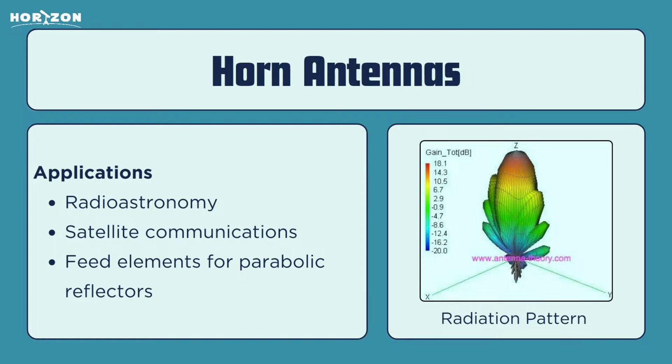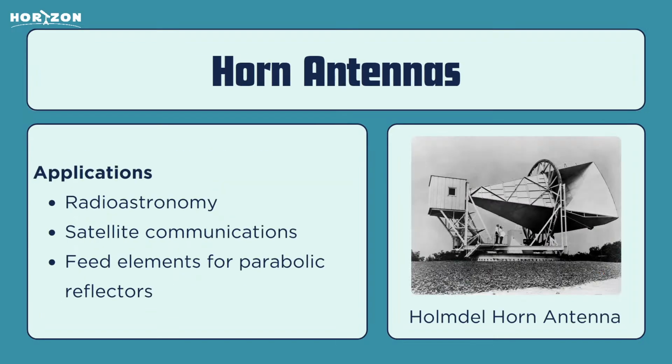Thank you. And now I will be handing it over to Kirtana, who will be covering a few more types of antennas, such as the helical and, oh wait, yes, I forgot about this. This is the horn antenna which was used to discover the CMB, as Kirtana mentioned earlier. You can see that its horn is actually quite large, and it allows for very slow and very gradual matching of the impedance from the source to the surrounding.